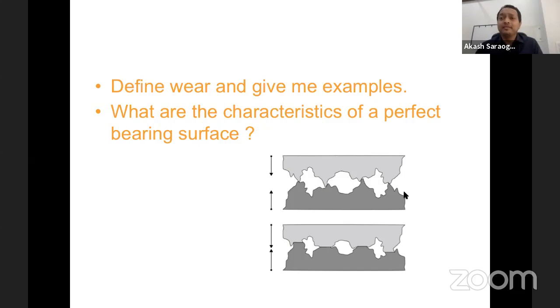What is fatigue wear? Small amounts of damage. Now, where do we see fatigue wear? TKR, knee replacement, plastic. Small microscopic wears within the entire material, especially just beneath the surface, which accumulate over a period of time. And finally, at some point in time, after the endurance limit, the material goes away. That is fatigue wear, also called delamination.